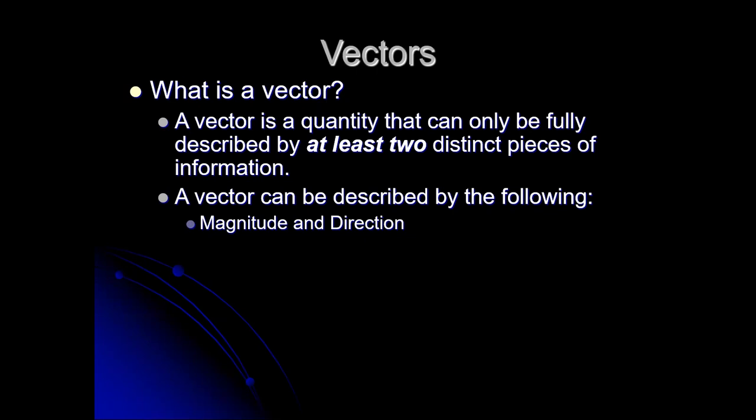If we're using our reversers and producing that thrust in the opposite direction, we're going to slow the airplane down. The direction matters. Think about thrust vectoring, for example. That involves taking the thrust, the force from the engine, and pointing it in different directions to obtain a new flight control. So magnitude and direction, size and direction are important quantities.